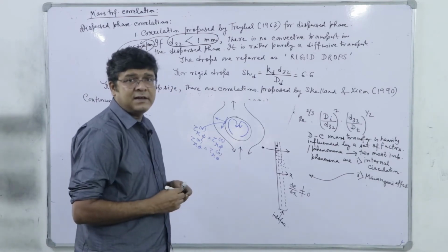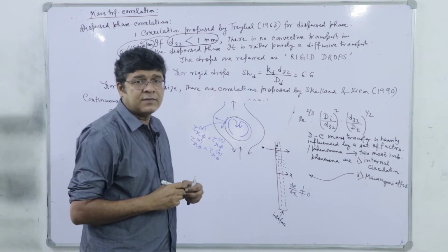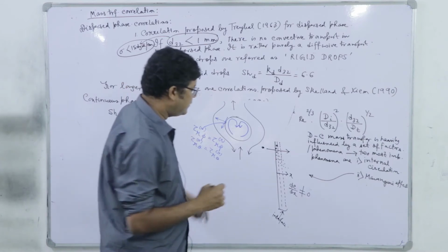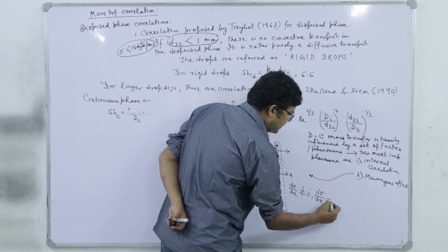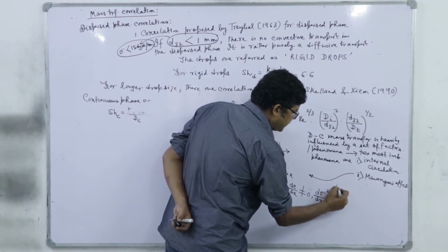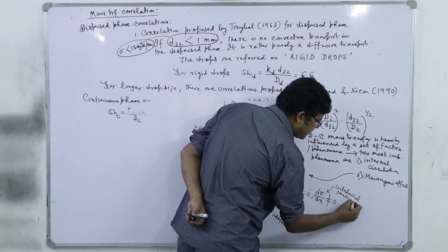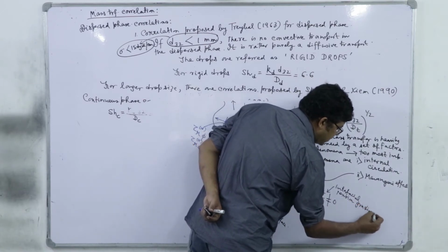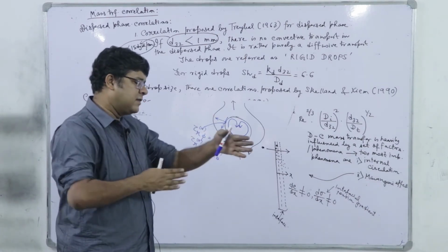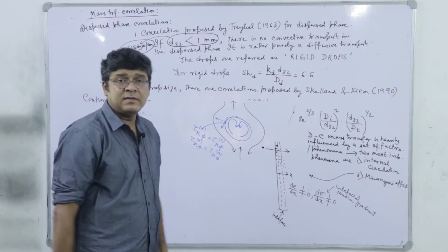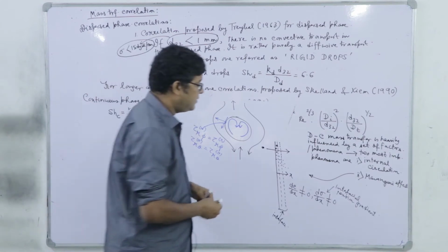Once we have a dc/dx, the interfacial tension, which is a function of solute concentration, will also vary. As a consequence we will have d sigma/dx, which is called an interfacial tension gradient. Because of this interfacial tension gradient, one layer starts moving over another, and it may even result in interfacial turbulence, which severely enhances the mass transfer rate.